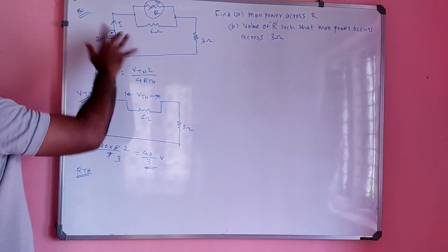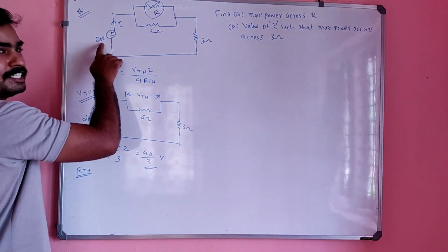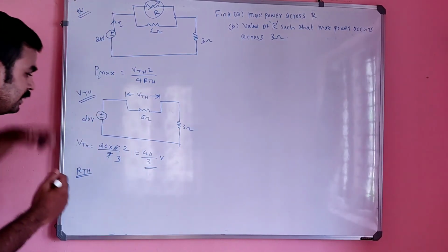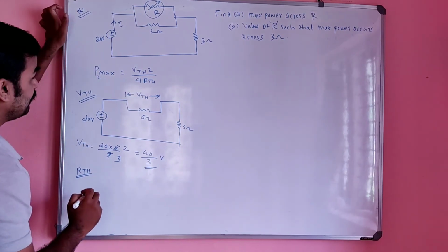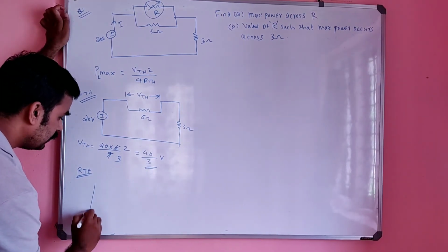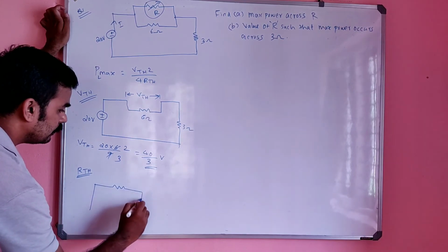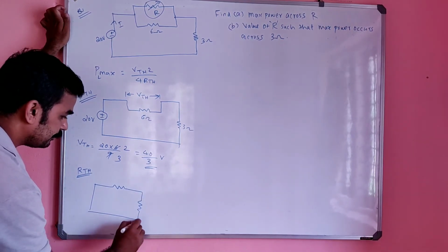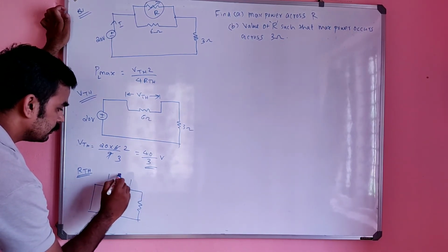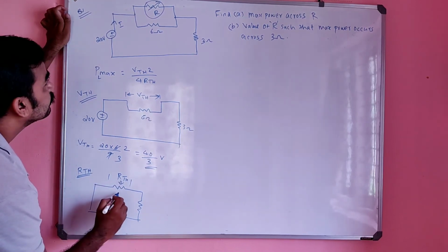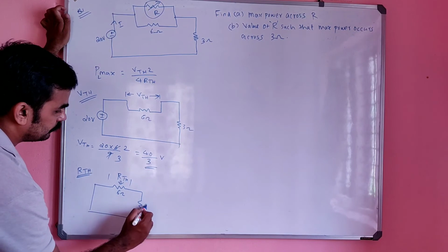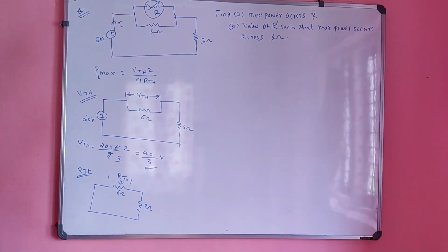Here only one independent source, that is nothing but 20 volts, so that to be short circuited, and R Thevenin will be right.